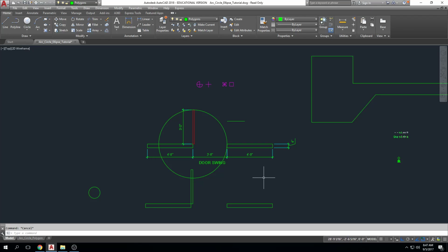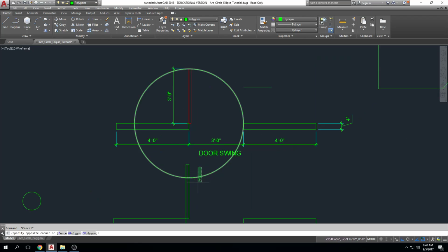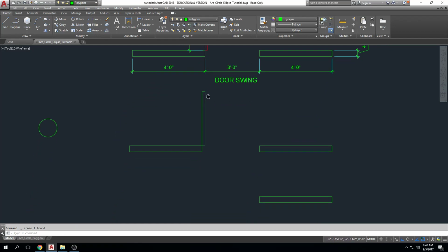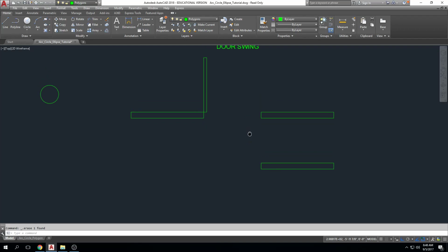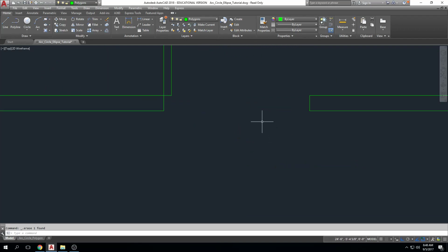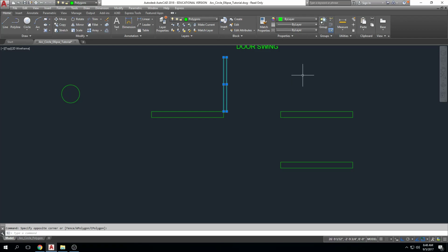One thing I want to remind you of is lines, arcs, circles, rectangles. When you draw these things, they're just geometry, right? So they can be selected, they can be deleted, right? They can be modified, okay? So I can grab any of these objects that I create with a selection window, right? Click, delete, and they go away. I can come down here, I'm panning, holding my middle button down and moving my mouse. I can zoom in, I can zoom out, I can grab these, hit delete, and they go away. Oh, we've got some little leftovers. Delete, delete, oh, delete, delete. Okay.